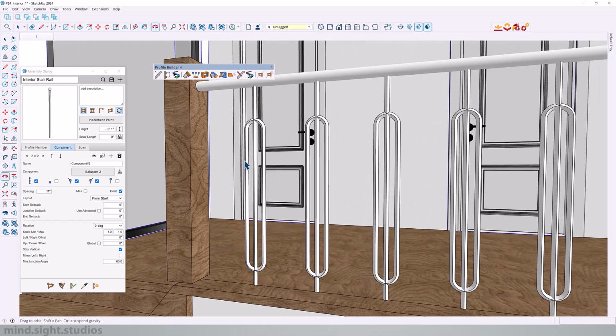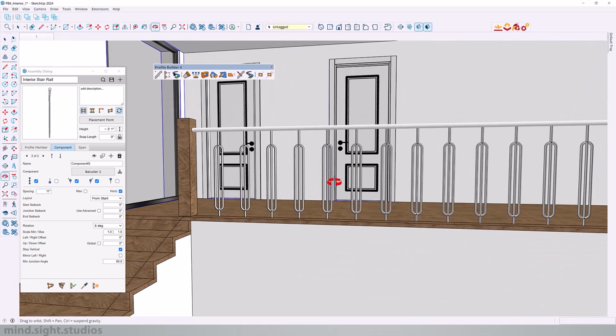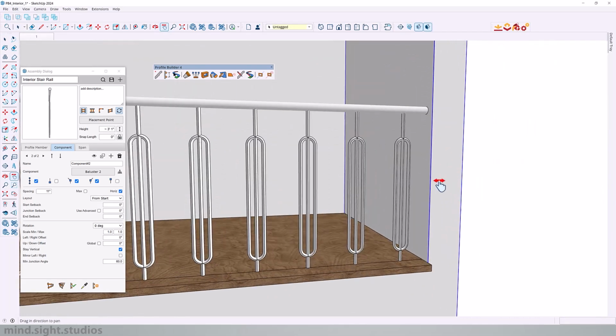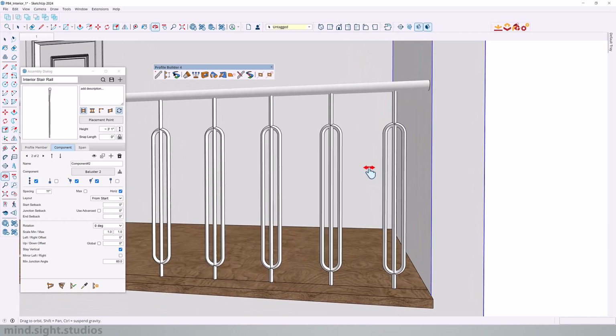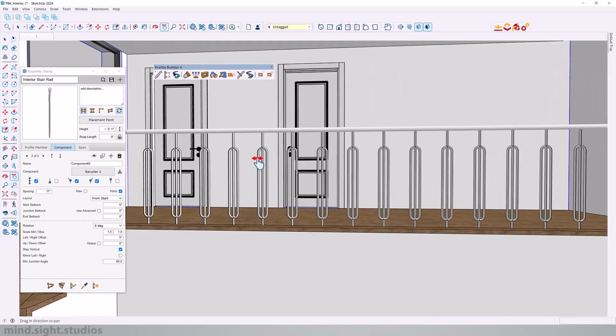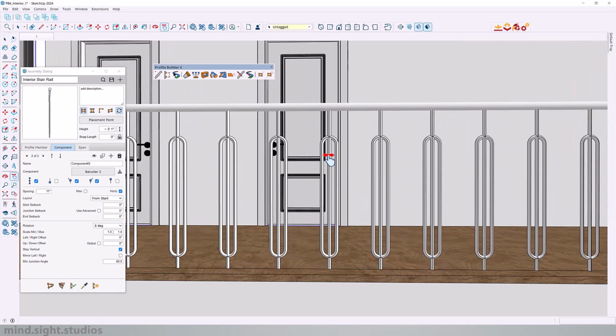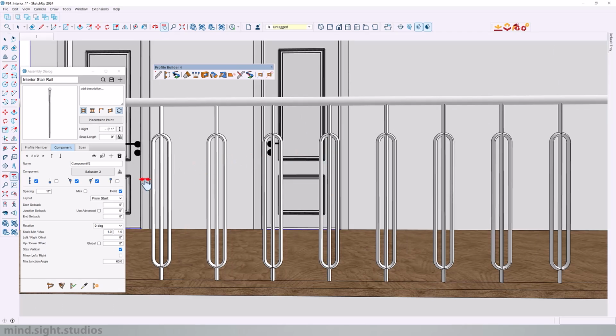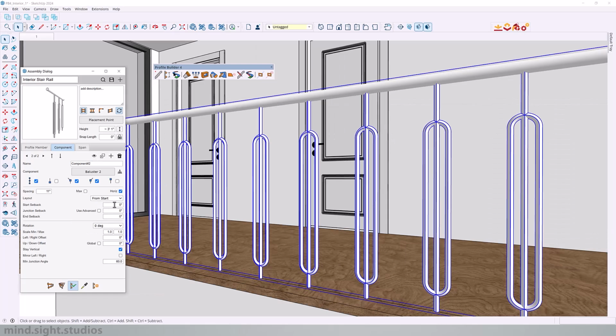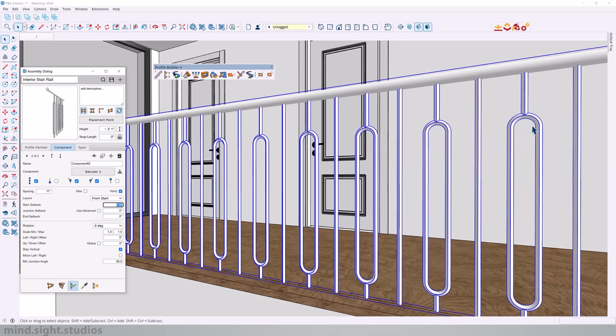So every setting we've adjusted so far has led to the components still being overlapped over each other. So to fix this overlap, all we need to do is change the setback of one of the components to start in the midpoint of 11 inches, which is equal to 5.5. So I will go over to my second baluster and change the starting offset to 5.5 inches.